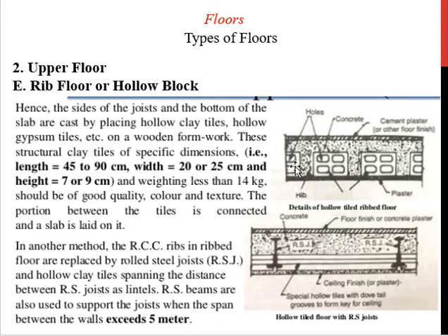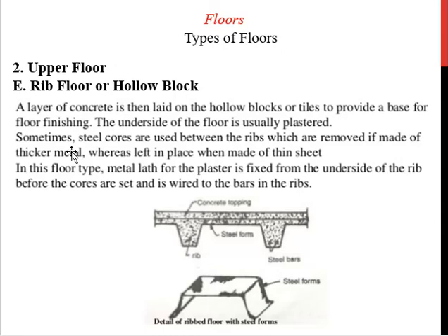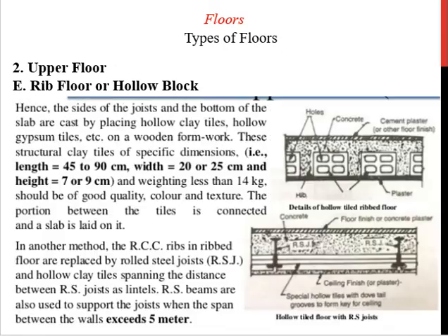and there are certain considerations regarding the minimum sizes and shape, depending upon the exact position of the neutral axis. We can work that out, and the civil engineer will get an idea where the neutral axis is, and on the basis of that, a certain section can be removed without affecting the strength of the concrete floor.